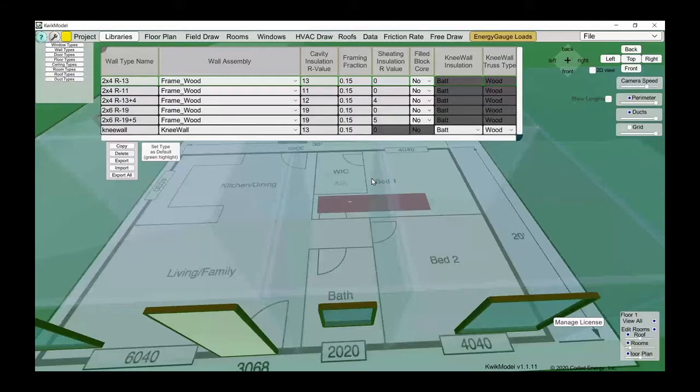And in the grand scheme of things, the difference between a 0.15 U factor and a 0.17, you'll hardly notice the difference. But it does matter between a 16-inch on center wall and a 24-inch on center wall. That's a lot less framing, a lot more insulation. So it should have an impact, and it does on the heating side, not so much on the cooling side.